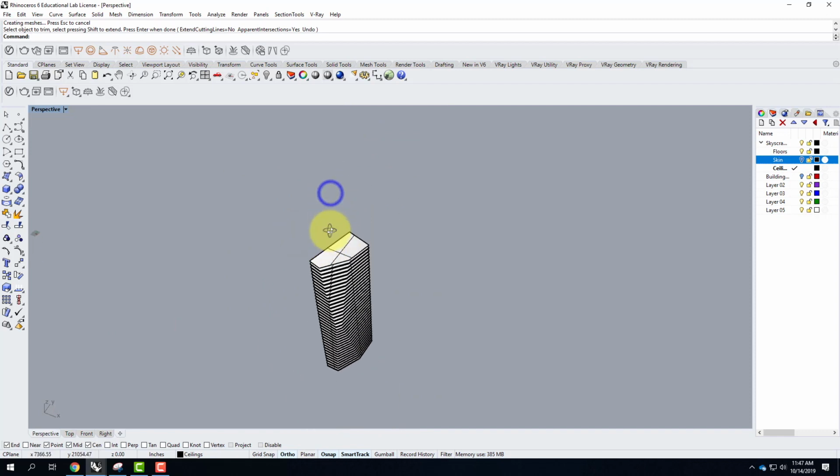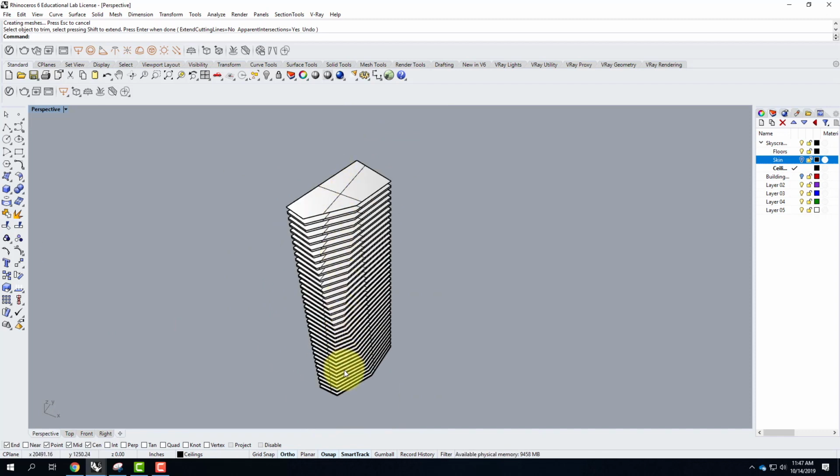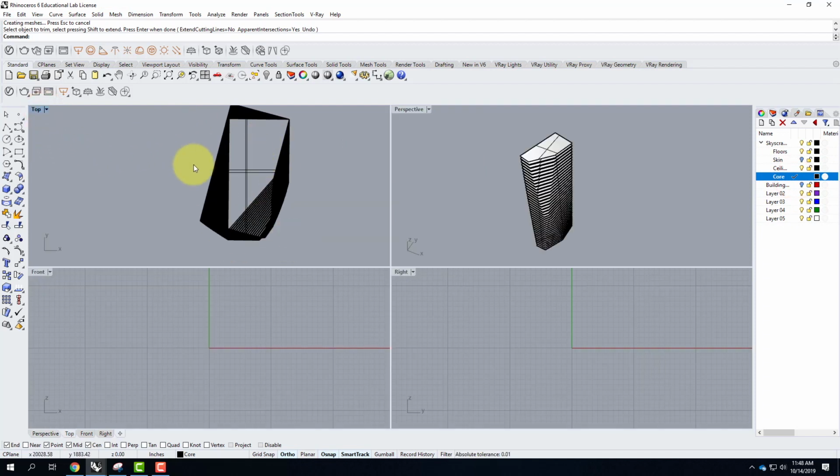So the next piece of this would be to actually punch an elevator core through the building. The elevator cores tend to be straight unless you have a really fancy elevator that goes on a diagonal or something. So we're going to go ahead and create that part. Using the skyscraper layer, I'll create a new sub-layer for core. I'll make that active.